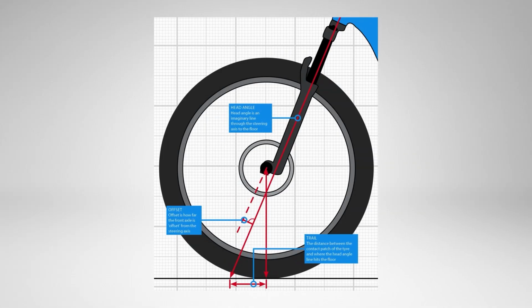Let's review bicycle steering as an example. Bicycles typically use a significant amount of positive caster. The caster trail is large as the point of load projects far ahead of the tire's contact patch. Do you recall how easy it is to ride a bike without using handlebars? You were able to steer the bike hands-free because the front tire followed your weight due to positive caster trail.